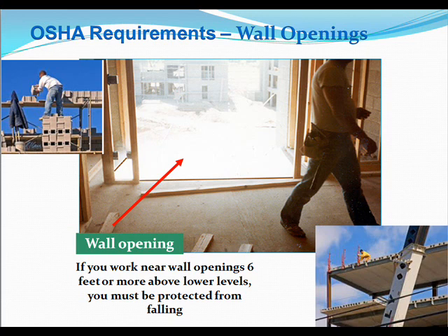Wall openings. If you work near wall openings 6 feet or more above lower levels, you must be protected from falling.